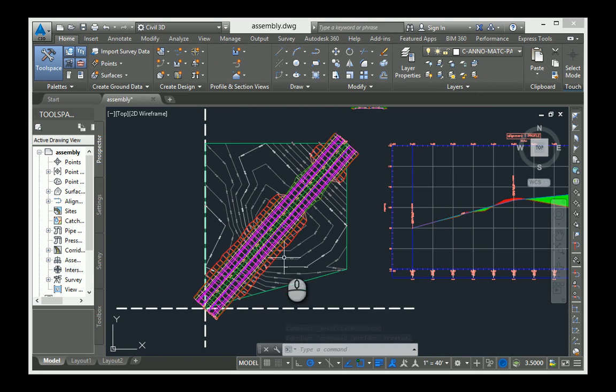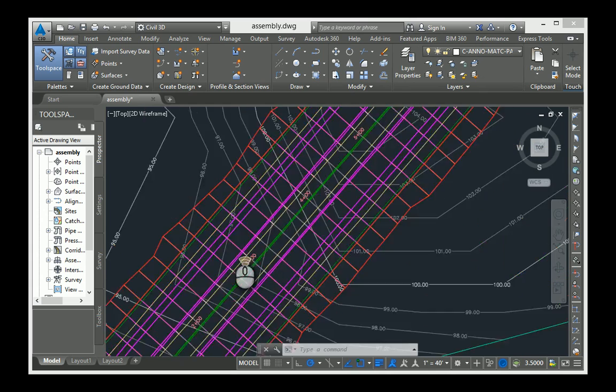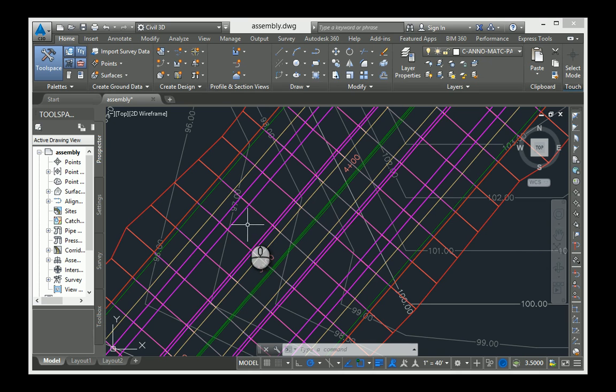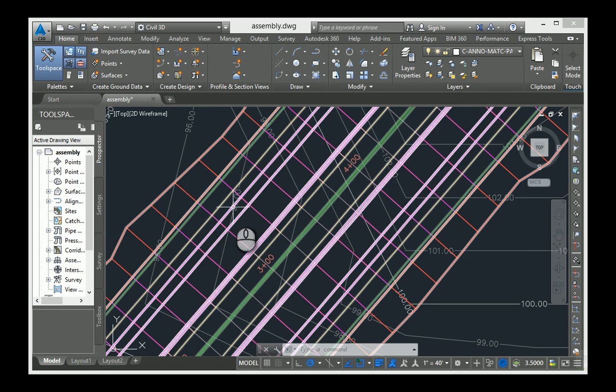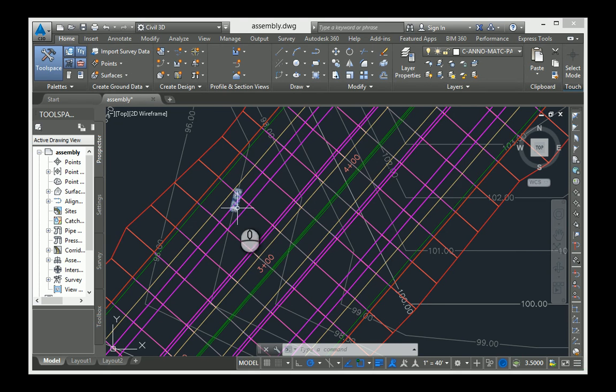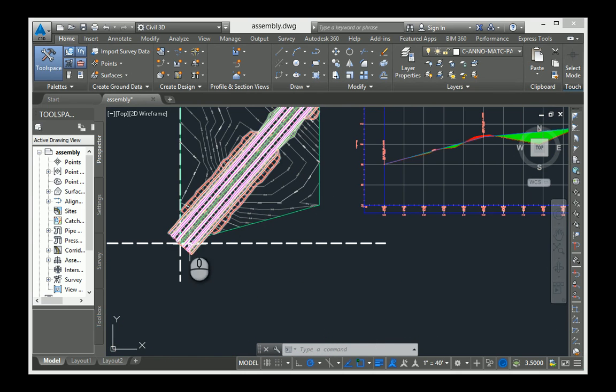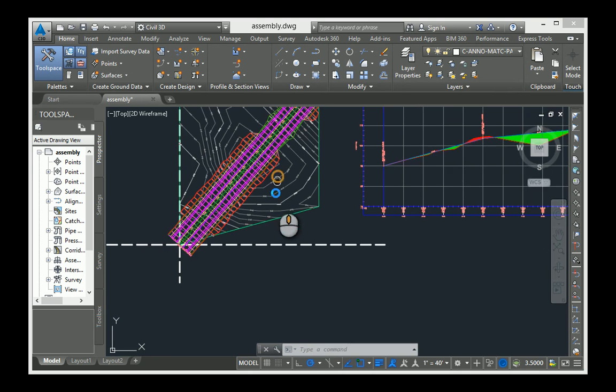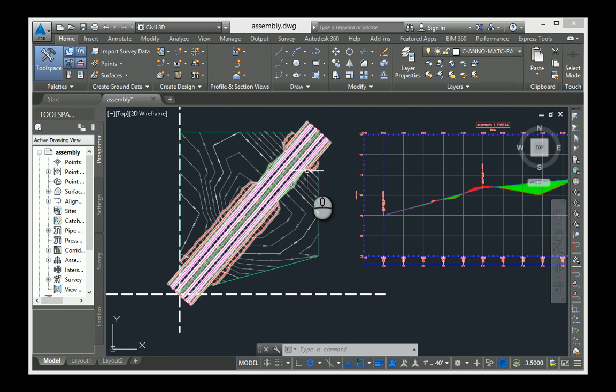So what is this showing? This is our two lanes right here, a little hard to see, but the cross here is the driving surface. This is the emergency lane surface. This is the shoulder. This is the bottom of the ditch, and then we slope back down or up to come back to the existing grade. So this perimeter here is the area that would have to be cleared in order to do all of this work.